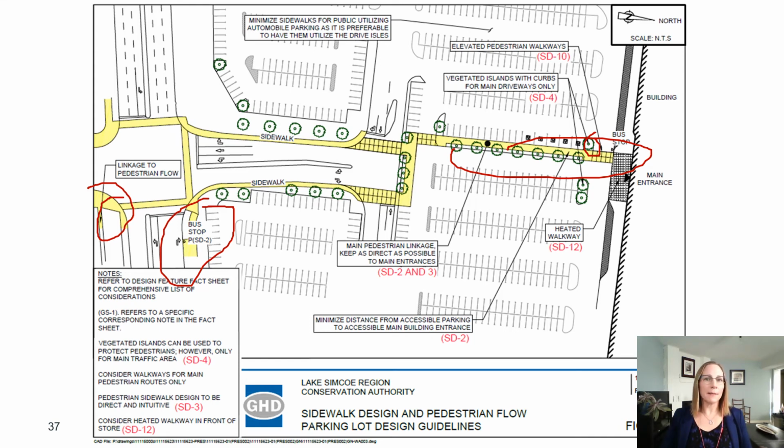Partially covered walkways like overhangs, which would present an issue on walkways due to roof drainage and refreezing, should be eliminated, but they can be replaced with centralized covered walkways and main building entrances where you can. The runoff from any overhangs, again, should be directed to appropriate stormwater management facilities and not onto paved surfaces. You could also consider designing the width to be at least 1.5 meters so that the snow can be removed by conventional equipment and not by someone with a shovel and a bucket just putting down salt willy-nilly, or not shoveling at all, actually, which is what happens in a lot of cases,